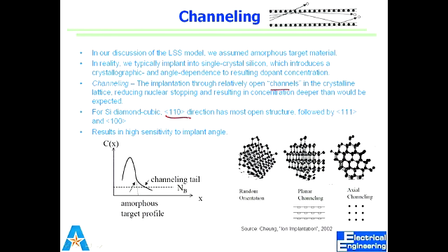So there are certain processes which are very specific, or they depend heavily on the orientation of the element. Some don't depend heavily. They show some differences with the orientation. Some have no effect with the orientation. Even in oxidation, if I do wet oxidation, that's so rapid that essentially my orientation doesn't matter there, right?